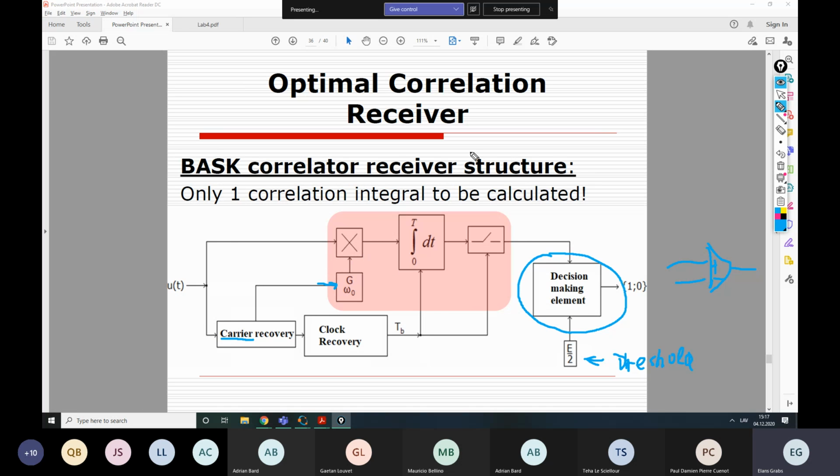We will not have such a problem in our practical exercise because we are going to reuse that signal carrier as 0, which we have generated. But of course, you must realize that for real systems, there is some distance in between, and it's often impossible to send this signal to be reused, right? So we need to extract it somehow from our received signal, and that's what the carrier recovery schematic does.